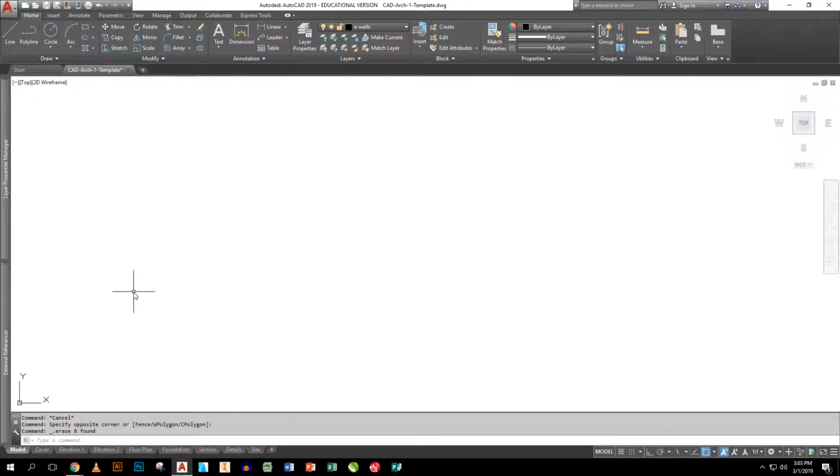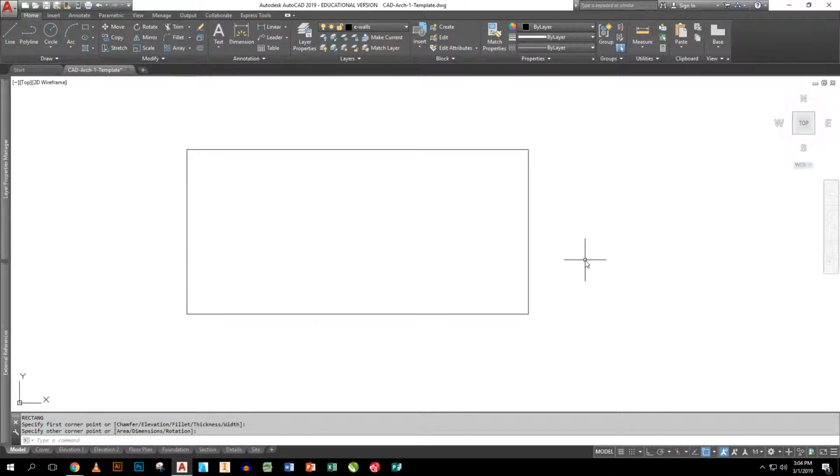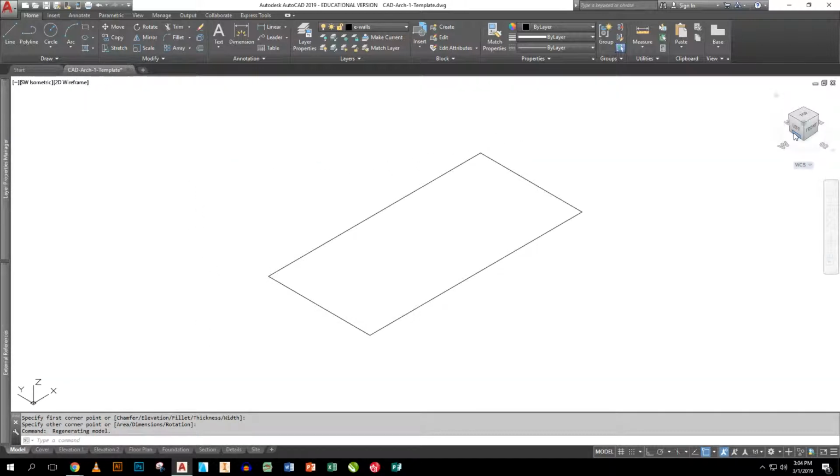It starts out with a standard rectangular system, but as you tweak it, you can end up all over the place. In fact, this right here, just like in Inventor or say Revit, this is our view cube or orientation cube. It can rotate us around and we can end up with all kinds of things. So like if I draw a rectangle right here, there's my rectangle. If I hit my view cube, watch what happens to it right here. It goes into an isometric view. Actually, it's a three-dimensional view.